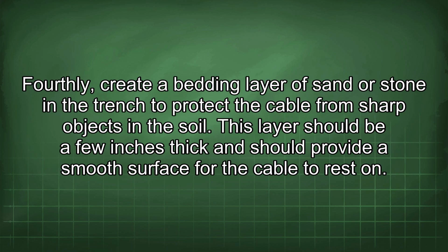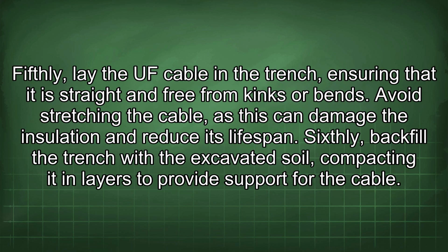Fourthly, create a bedding layer of sand or stone in the trench to protect the cable from sharp objects in the soil. This layer should be a few inches thick and should provide a smooth surface for the cable to rest on. Fifthly, lay the UF cable in the trench, ensuring that it is straight and free from kinks or bends. Avoid stretching the cable, as this can damage the insulation and reduce its lifespan.